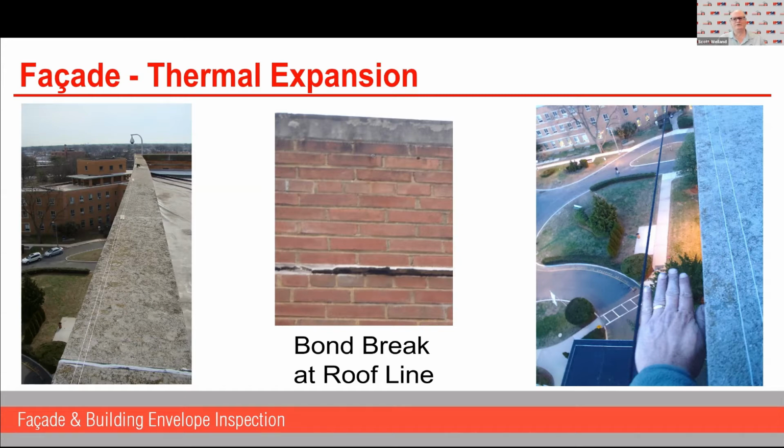It buckled about 3 or 4 inches, and what helped it buckle was there is some through-wall flashing that served as a bond breaker that allowed this parapet wall to kind of lean over.